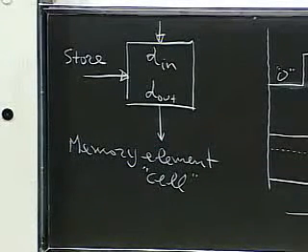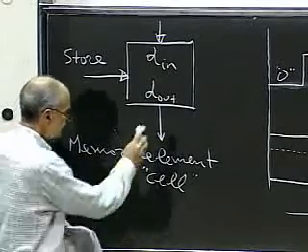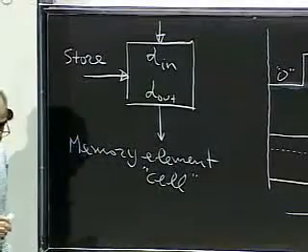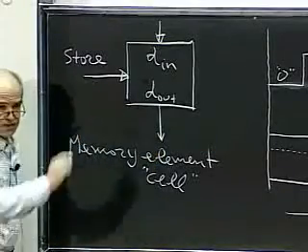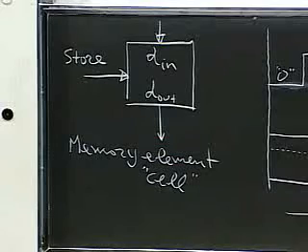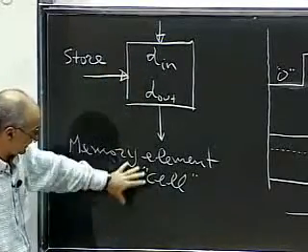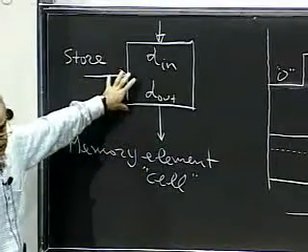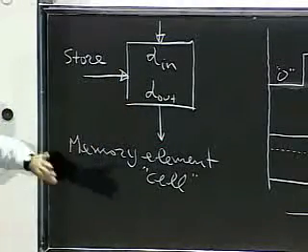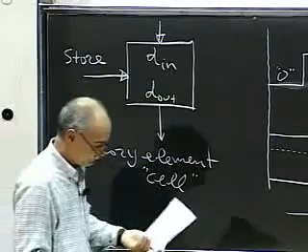It would remember the output state. And not only that, but in principle, it should be undisturbable, okay? In other words, I may do something to this D out, but it should not flip the state. And that comes about quite a bit because in actual integrated circuit memory, there's lots and lots and lots of nearest neighbors to this cell, which, when they're flipped, have a cross-coupling to this cell. The cell must be designed robust enough that it doesn't flip, okay, that no coupling actually occurs.